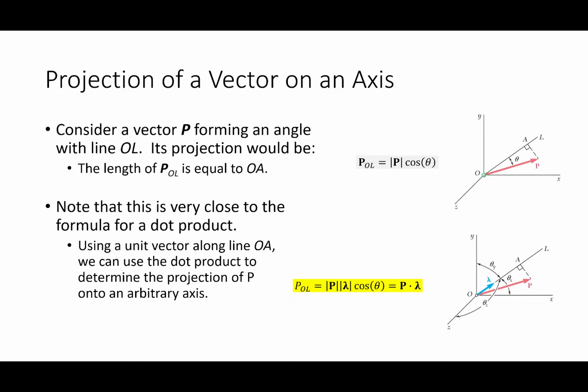So this vector says I want to rotate 200 Newton meters this way, 300 Newton meters this way, and instead of 400 Newton meters this way, it's going to be 400 Newton meters that way. Why is it backwards? Because it's negative. So what this vector is representing is the tendency to rotate about the x, y, and z axes. That's what these scalars represent, the 200, 300, and 400.